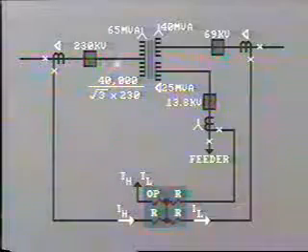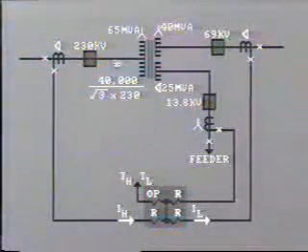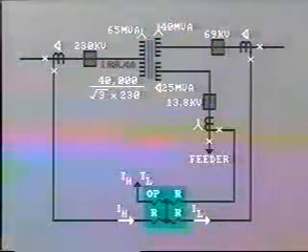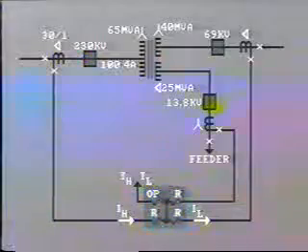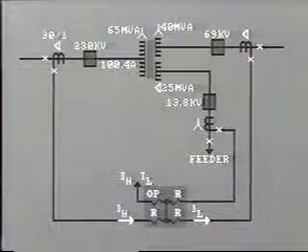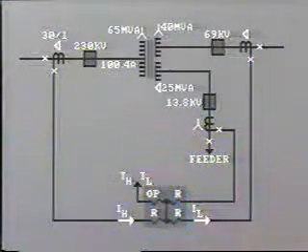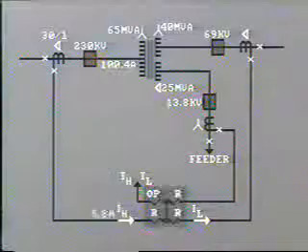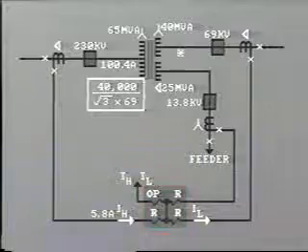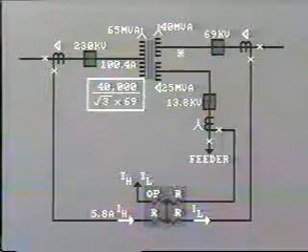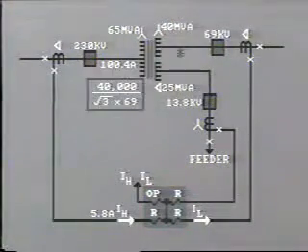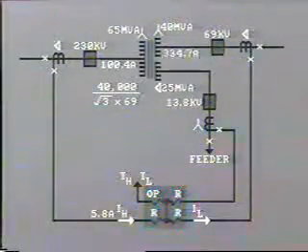The line current in the primary will be 40,000 divided by root 3 times 230, which equals 100.4 amps. Assuming a CT ratio of 30:1, and remembering that the CTs are delta connected, the secondary current equals 5.8 amps. On the secondary side, the current in the transformer windings will be 40,000 divided by root 3 times 69, or 334.7 amps.